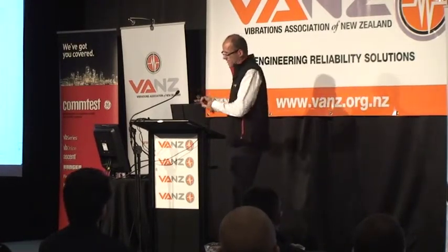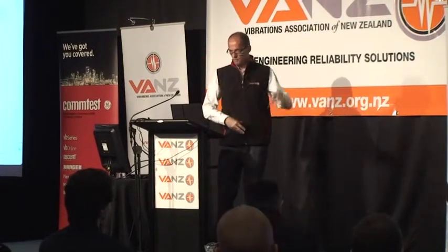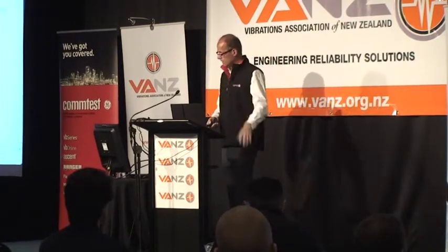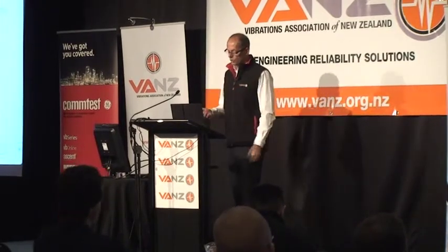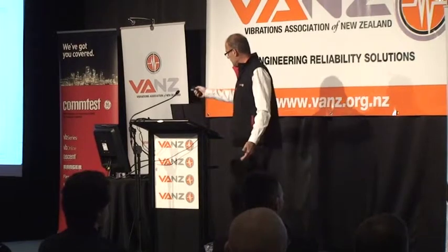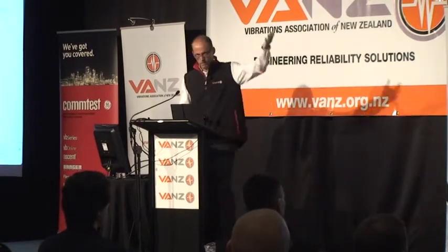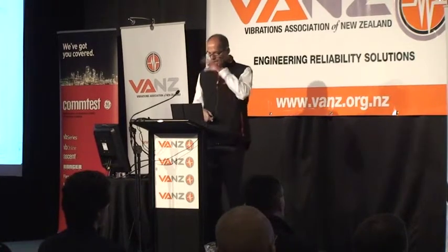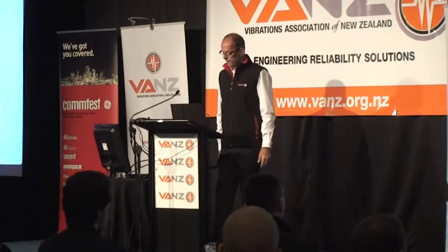If you just scrap the bearing, how would you ever know? You just think the job's done. Okay, I've replaced the bearing, job's done. Well, it's not done. And this is why we're trying to improve reliability by eliminating these root causes. In this case, you can see the little spark at the top and bottom of the bearing, there is current flowing through the bearings. And it leaves that etching on the bearing, and it'll eventually fail.